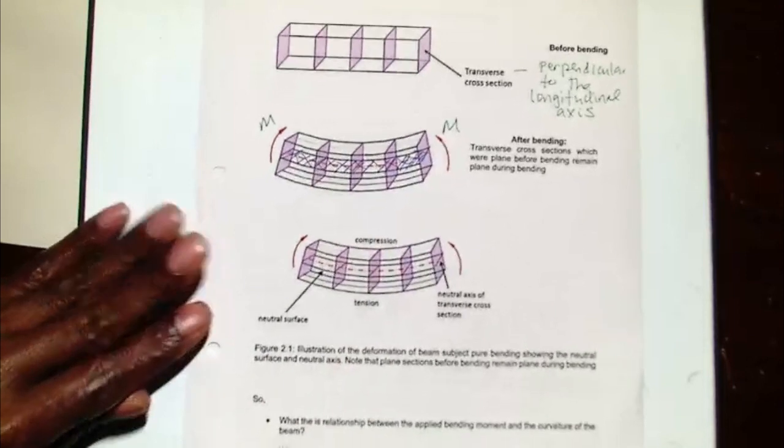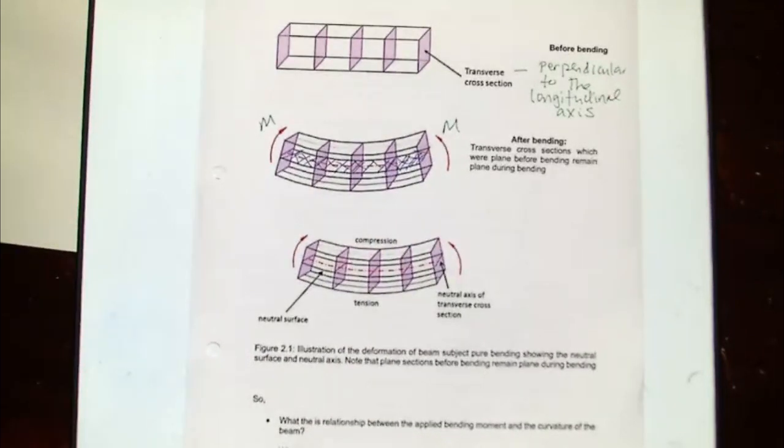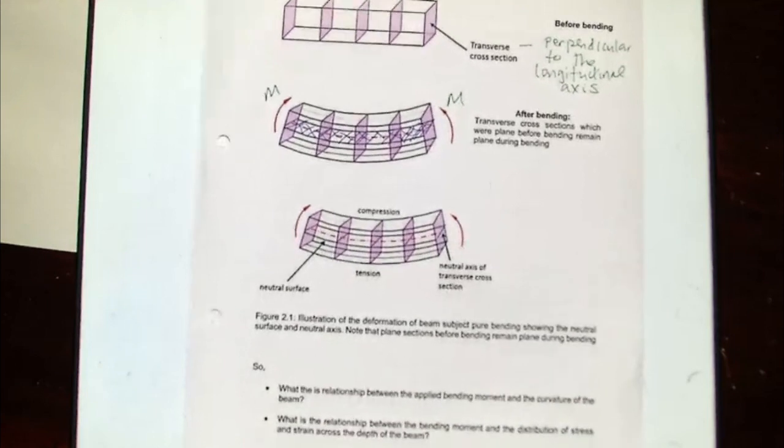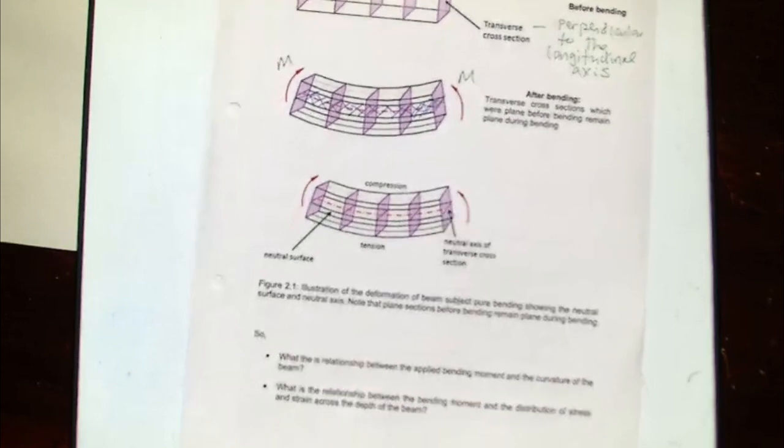From now on, you'll be hearing this term neutral plane. It means it is a plane along which there's no bending stress at all. So we go from tensile to compression, we have to go past that neutral section. What we want to show now is the relationship between the magnitude of the bending moment M and the stress that we develop going from the tensile to the actual compressive side of the beam. Are we clear about that?